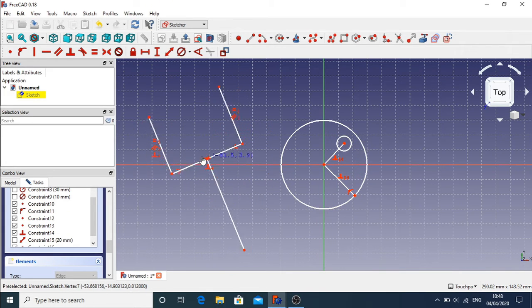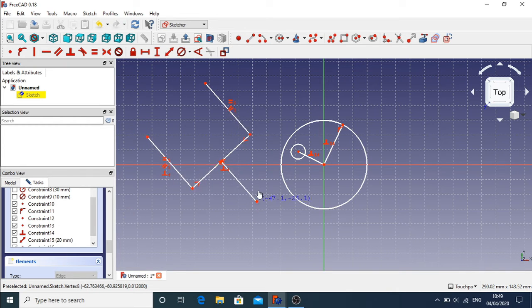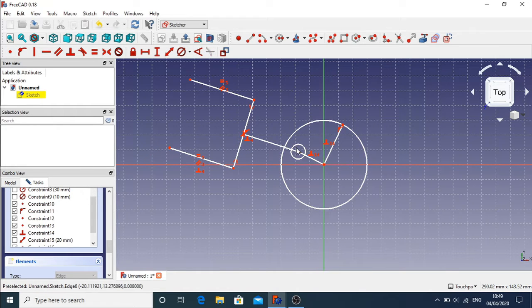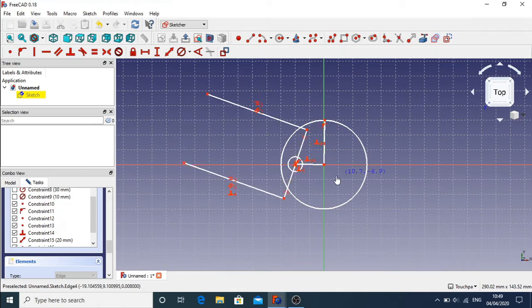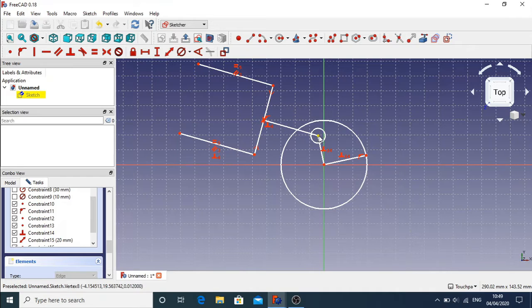And we've got our other object here. So obviously rotating the sketch like this has an effect on other objects that are constrained to the geometry that you're rotating. So if I moved this over here and constrained those 2 points, when we rotate this now, our other geometry will rotate as well.